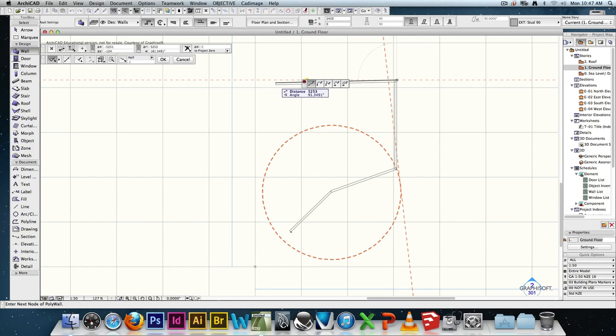Now I'm going to talk about this a lot in the next assignment, but be very careful when you do measurements like this, where it's one measurement on top of another, on top of another, because every time you do that, you're increasing your error. So if you measured this entire building, which we may or may not be doing for the second assignment, I haven't made up my mind yet, if you started at that corner and just measured 4 meters, 2 meters, 3 meters, by the time you got to the other side, you would be so far out it wouldn't be funny. You'd be out by meters because all the little errors in between will add up.